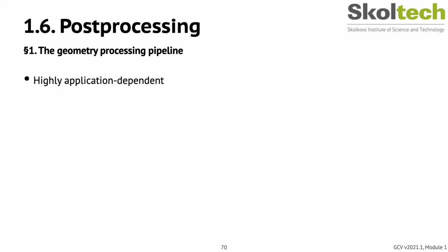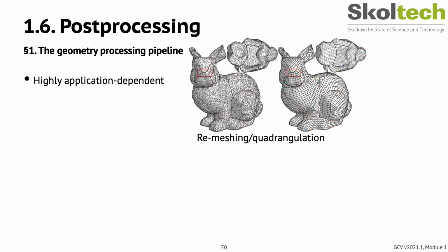The post-processing algorithms that are executed on the resulting triangular meshes are highly application dependent. For example, partitioning the surface into quadrangle rather than triangular tiles is a common requirement in computer graphics, where such quad tilings are amenable to a variety of subsequent applications due to their tensor product nature, such as B-spline fitting, simulation, texture atlasing, and rendering with highly detailed modulation maps. Converting a triangular mesh into a quadrangle mesh is known as quad-dominant remeshing or quadrangulation.